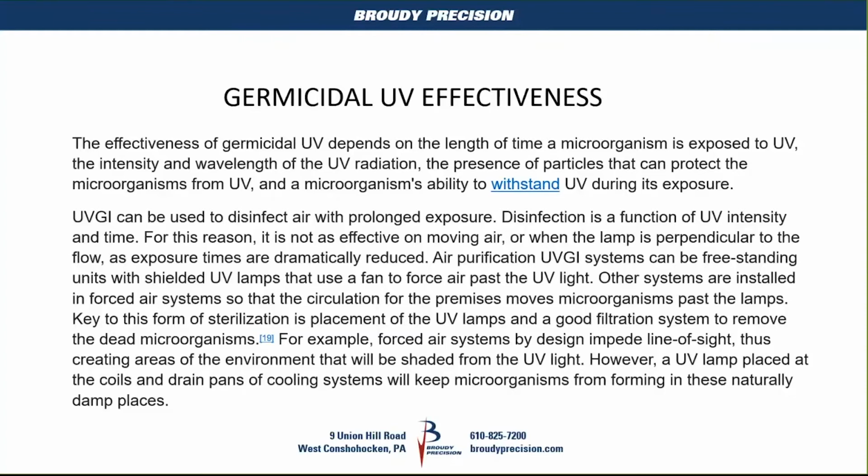That's why with surface stuff, you're going to have a greater chance, because you can control the amount of time that you can direct the light on that surface. But we're not as effective when we're moving air, because there's a bunch of different variables. If the lamps are installed perpendicular to the airflow, you're reducing the amount of time that the air is in contact with that light wavelength. Whereas if you're with the airstream, you're going to be exposing that airstream for a longer period of time.